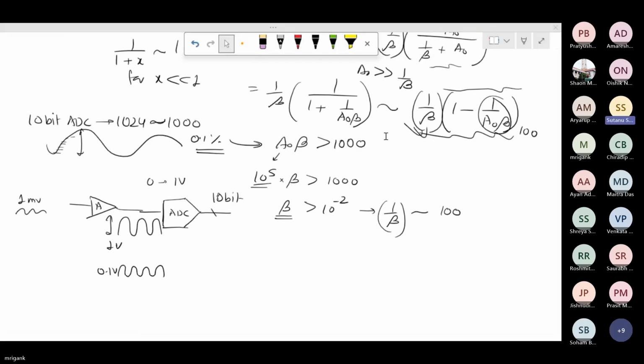Sir, the ADC has 10 bits, right? So it has a resolution of 1024. So the signal which the ADC receives will basically be split into 1024 parts. Now if I have magnified only up to 0.1 volt, there may be loss of data, while if I amplify it to 1 volt, the chances of loss of data are less.